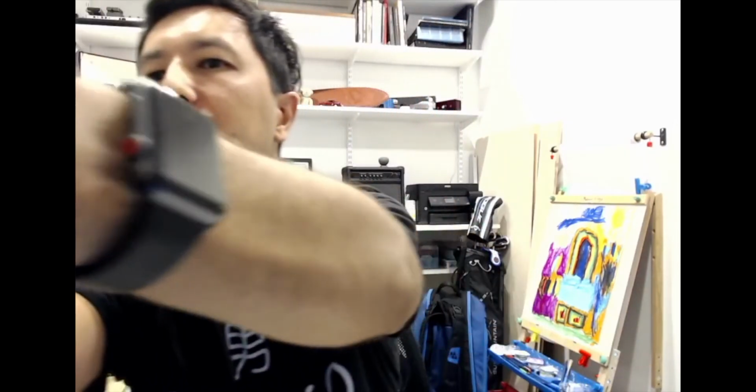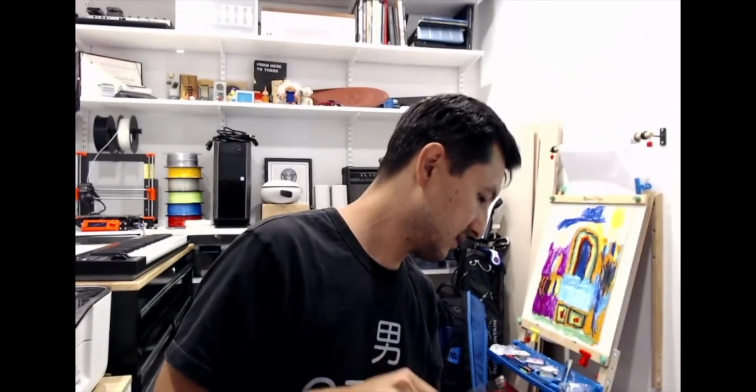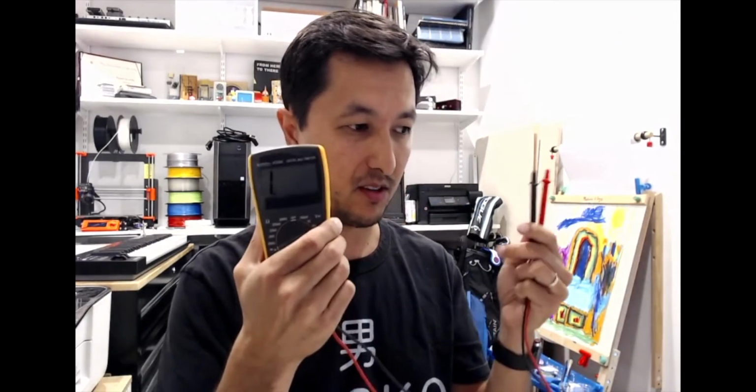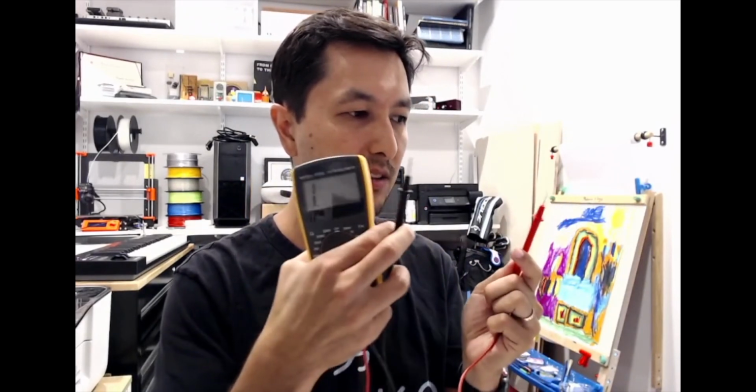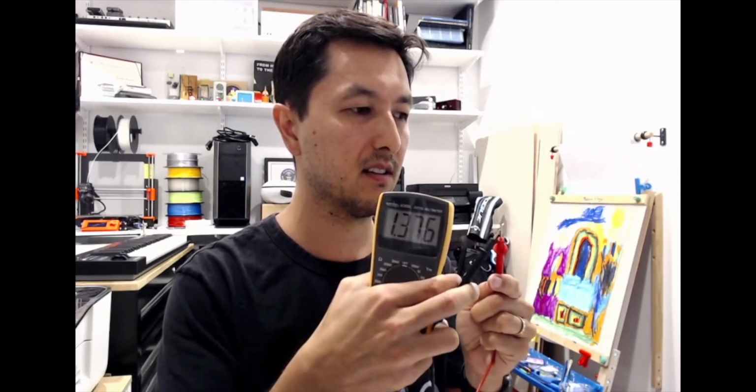Nothing is beeping for me, so oh, there we go. I got something that's conductive. It's a clamp that's holding up my camera. I thought my wrenches would be conductive, but they're not. Sometimes there's a coating on top of the metal that removes the conductivity. So if you have a digital multimeter, that's a really great tool to see if something is able to conduct electricity or not, just by touching it with these two leads. And then it should beep if it's conductive.